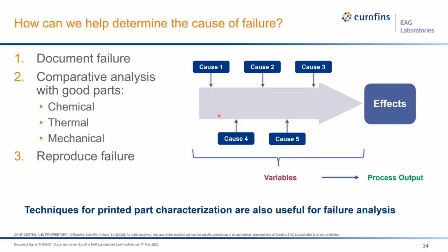Okay, so I completed discussion of the 4 case studies. And I just want to now say a few words about our approach to failure analysis. How do we try to solve these problems? We get a lot of interesting problems, and what do we do? So we always want to start by documenting the failure. What happened, right? We take optical pictures, images, maybe microscope images if needed, but we want to understand, is it a broken part? Is it a cleanliness issue? What is the failure?